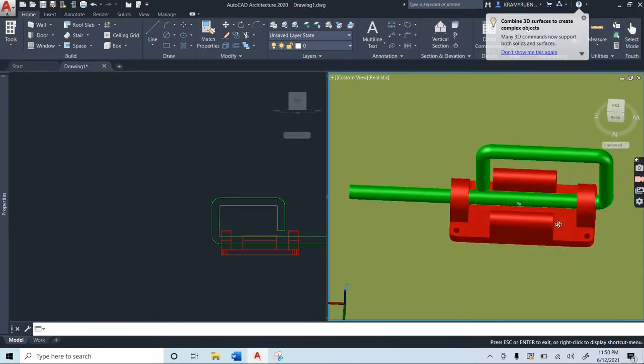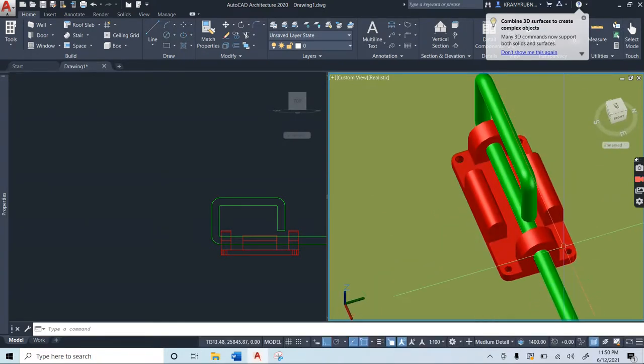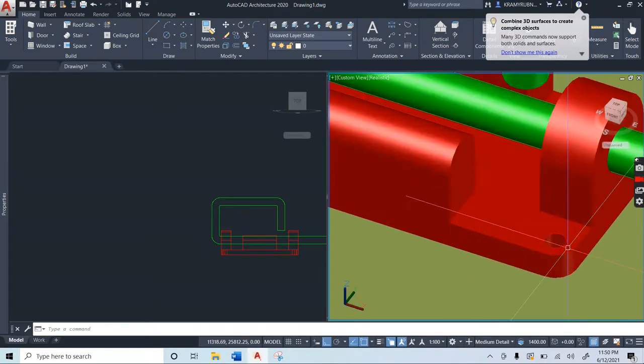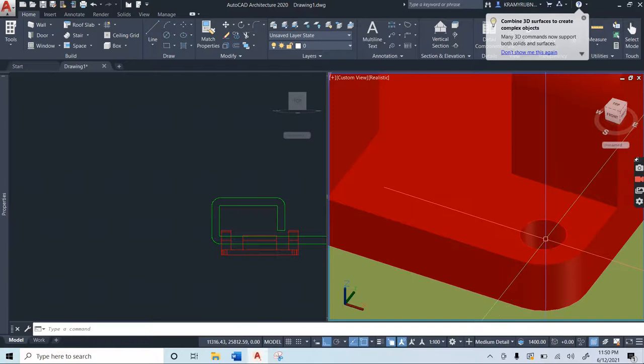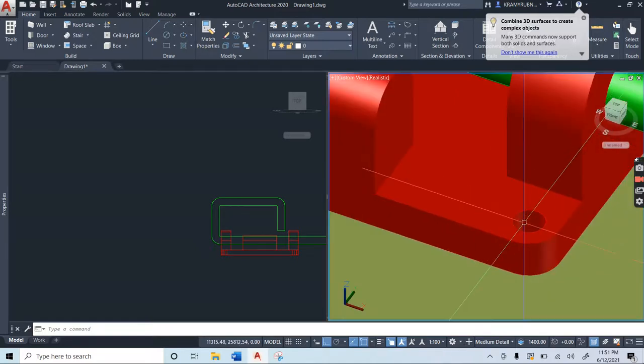and ready for use. You should also now be able to design pins, or from other tutorials that I have out there, you should now be able to view those. Even if you wish to give chamfer or fillet to our holes, we could just go fillet, and you might want to fillet those with radius perhaps about 1 or 2 millimeters.